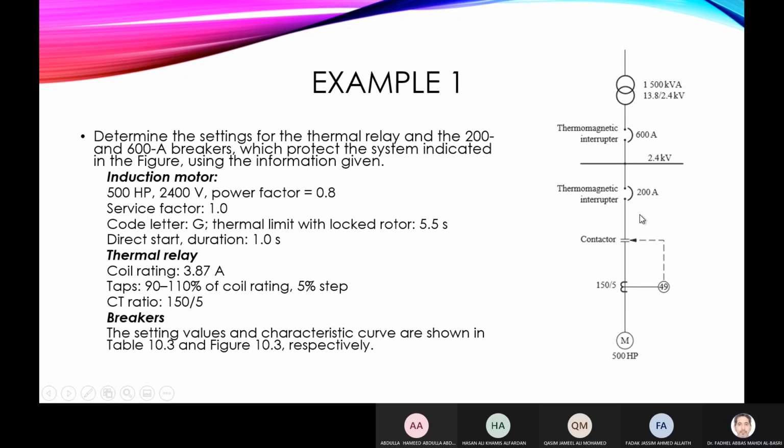Now, this circuit breaker is not like the circuit breaker for high voltage. A circuit breaker for high voltage doesn't have that. It means the relay and CTs provide triggering for the breaker to open during short circuit. In these low voltage and some medium voltage breakers, the protection elements are integrated within the breaker itself.